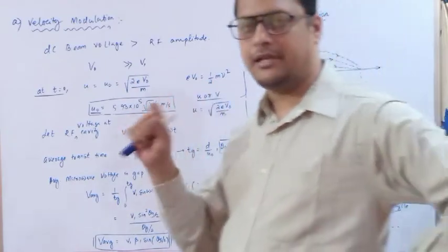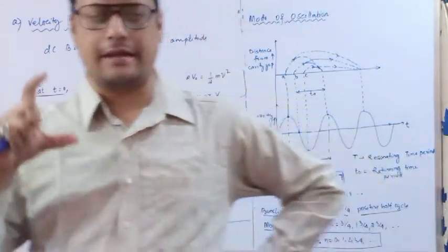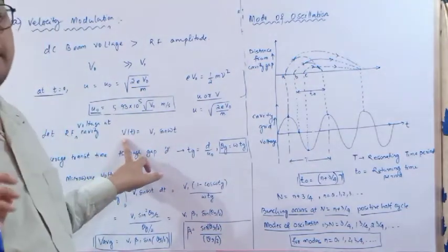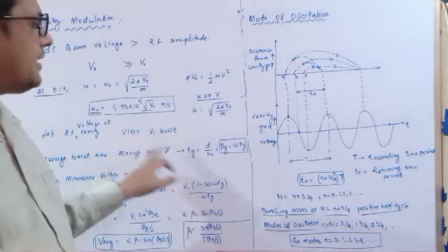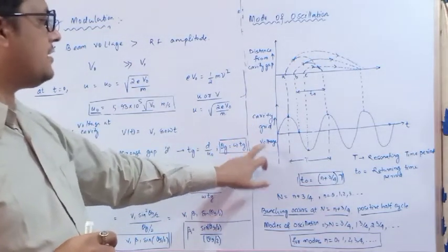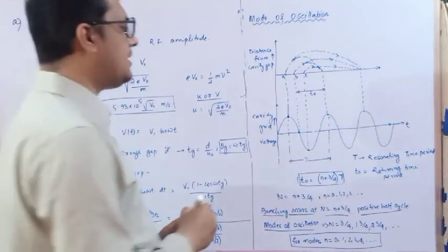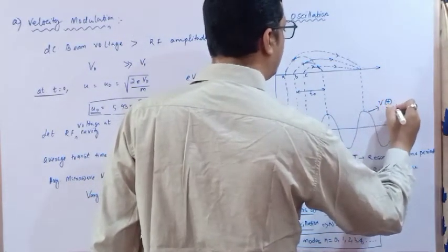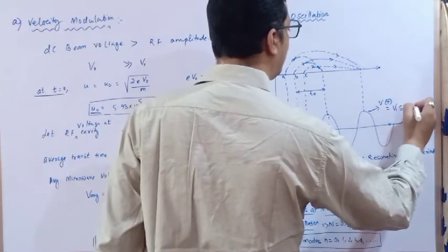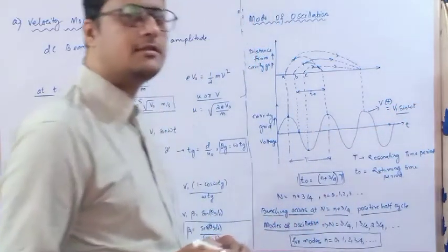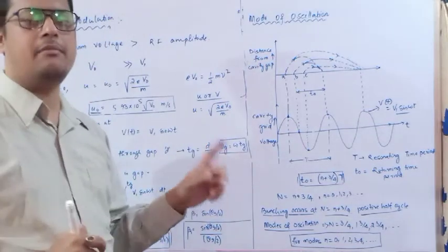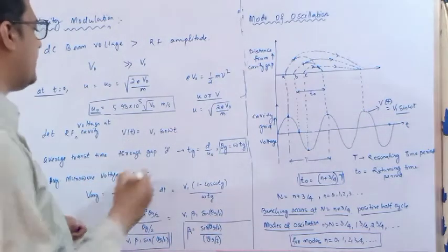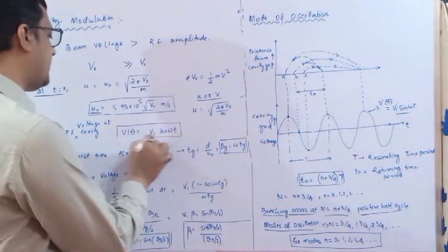that cavity gap d, small d, we have seen. So at the cavity gap, the RF voltage is provided as V of t with a potential V1 that we have seen. So it is a sinusoid signal. Here you can see the cavity grid potential, it is a sinusoid signal. So I am writing V of t equals V1 sin omega t. Done. So this is called my cavity gap potential, which is also called the RF potential. So it is V1 sin omega t. So this is the first assumption.